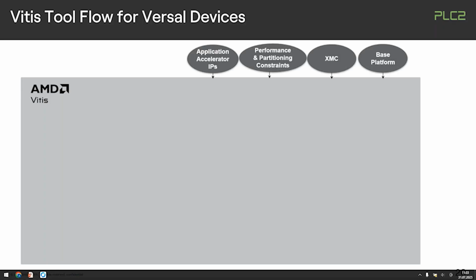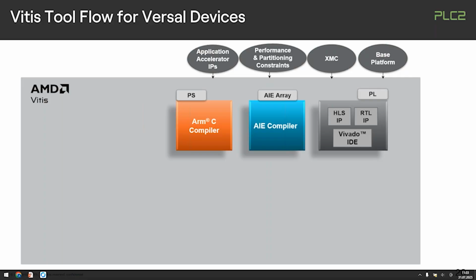different tool flows, of course. So you have all kinds of base information that you need to go into, and you will basically then have all the different tool flows to translate this information, like source codes or models, whatever you have in this case. There's a lot of different tool flows that can map out to the different endpoints. Very typical, of course, for the ARM-based CPUs, you will have a GCC or even an ARM compiler in this case that would simply just create the ELFs.